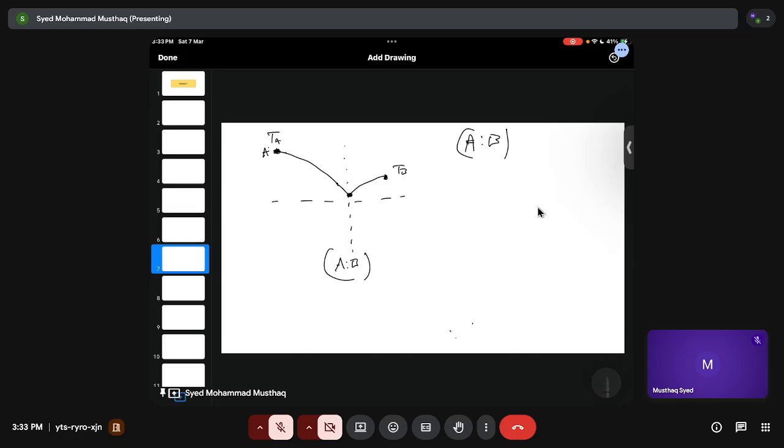Let's say TA is 1500 degrees centigrade, TB is 1400 degrees centigrade, then TE, the eutectic point, is 1200 degrees centigrade. So it will decrease your melting temperature. That is one good advantage of the flux, reacting with impurities to form slags that have a much lower temperature when compared to your initial phases. So that is about flux.